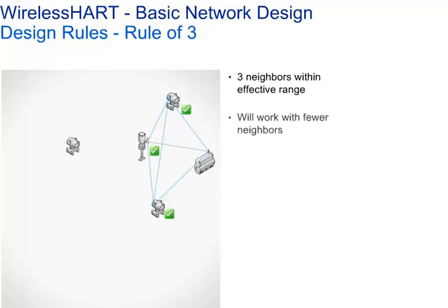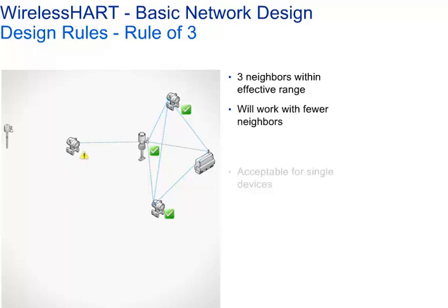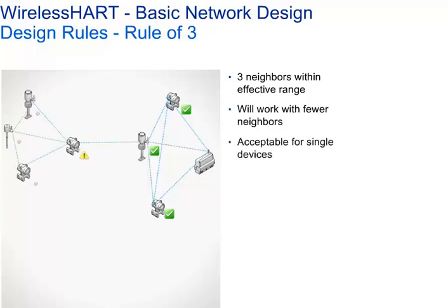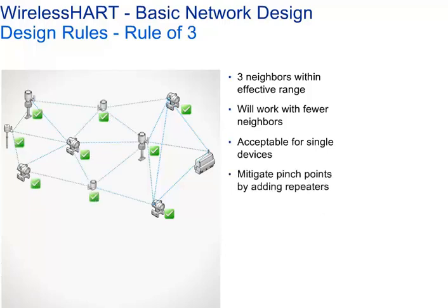Of course, devices will work with just 1 or 2 neighbors, but with less redundancy and diversity. While this is acceptable for single devices, this is inadmissible for routing devices. A pinch point like this can be mitigated by adding additional WirelessHART devices to work as routers or repeaters.